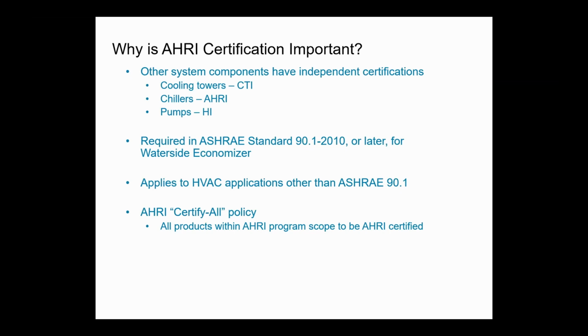But for right now, for instance, I'm working with ASHRAE 15, the safe handling of refrigerants. They're working on a section for revising the charge limit for A2L, A3 refrigerants, and there's an addendum going out where they're looking to raise it for 290. I'll get to that.